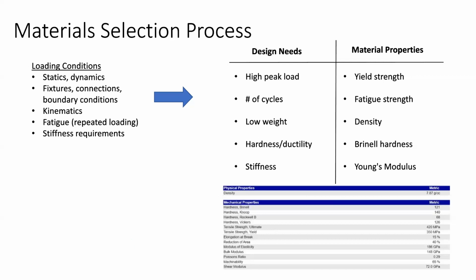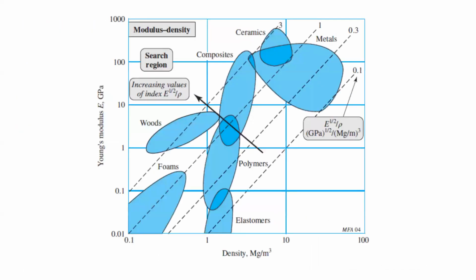In contrast, if you look at something like the suspension, you would still want a similar property such as high stiffness, right? But you're not really going to care about the weight as much, I would argue, because a lot of the components are so small that you care more about something like the peak loading and the number of cycles as opposed to the other requirements. So in a holistic sense, that's why we choose different materials for different systems. They have different fundamental requirements. And if you can see it from a really high level, you're in a lot better position to select a material.